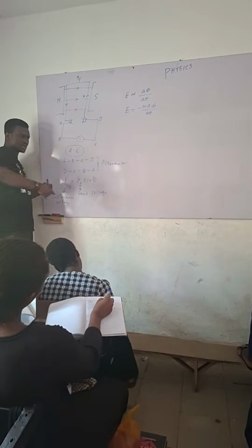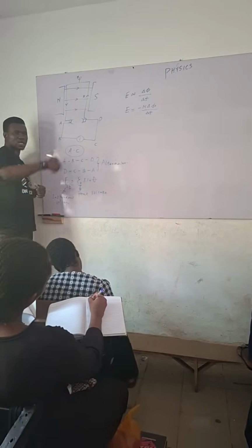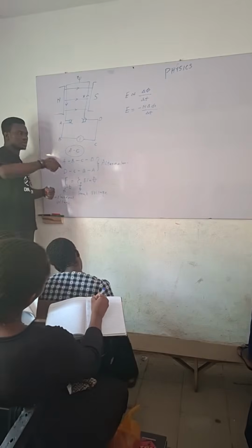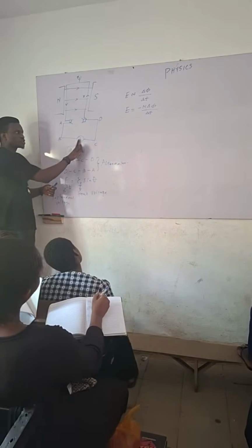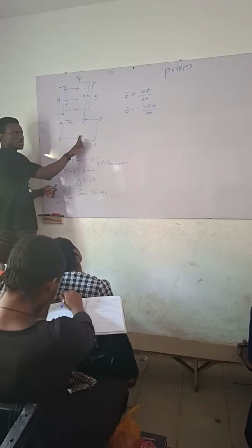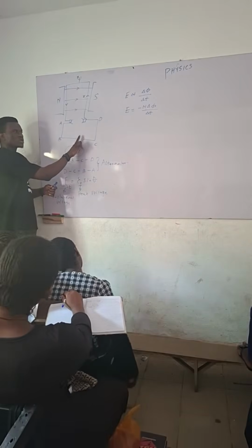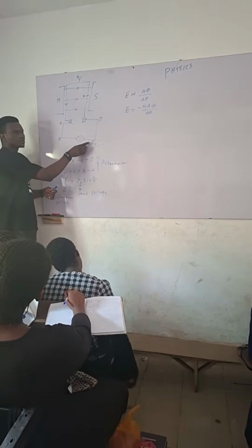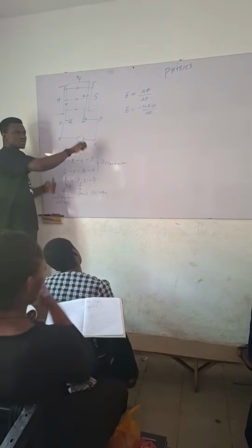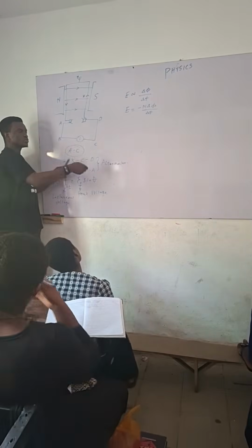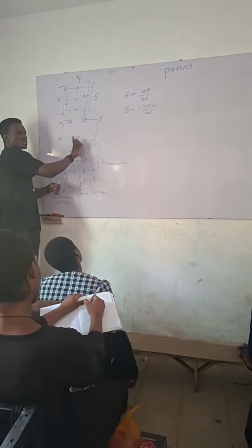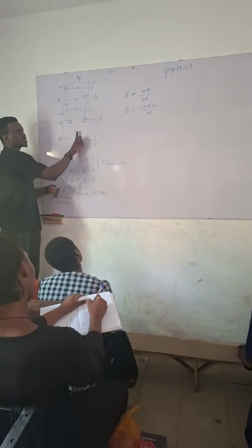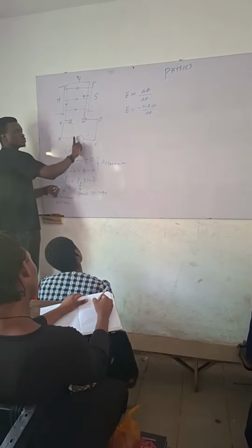As you are rotating it, you are cutting through the flux. And as you are cutting through the flux, flux is changing. Voltage is also changing. So the deflection will start from 0, then it will be increasing. Abby? So it's not like it will just bam. It will keep increasing as you are changing it. Then when you're changing it back again, it will go back again in this direction. So you see that this line will keep deflecting to the right, to the back.